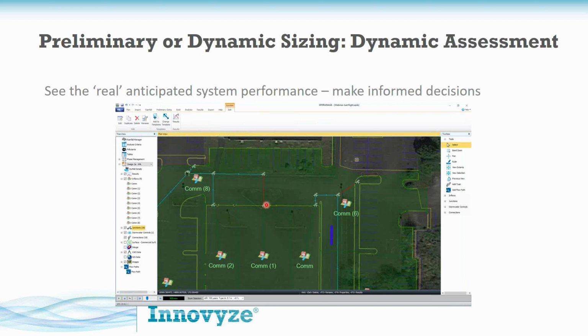We'll see also, I mentioned that there's that table that had those red flags saying, hey, this might be a problem. Well, we're also going to show this in plan view. So I'm looking at my model, and you can't miss that there's a couple sticks of pipe that are a different color. Hey, these perhaps are undersized, is what this is saying. So you can investigate.